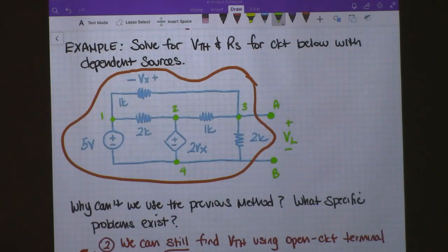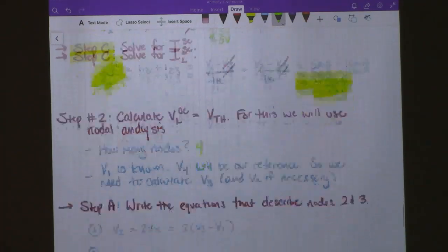Yeah. So the short answer, you're exactly right, is KCL is what we're going to apply, because we're doing nodal analysis. There's no voltage source at that node. So I'll label these real quick: I13 again, I23, I34. All right, so we know that I13 plus I23 equals I34.